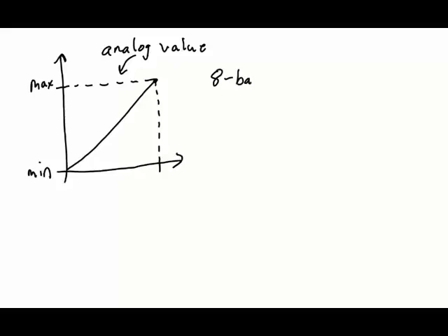I'm assuming this because working with 8-bit values will be useful to us, because 8-bit values make up a byte, and a byte of data can be sent at one shot over a serial connection. We now have to find something called the quantization value.